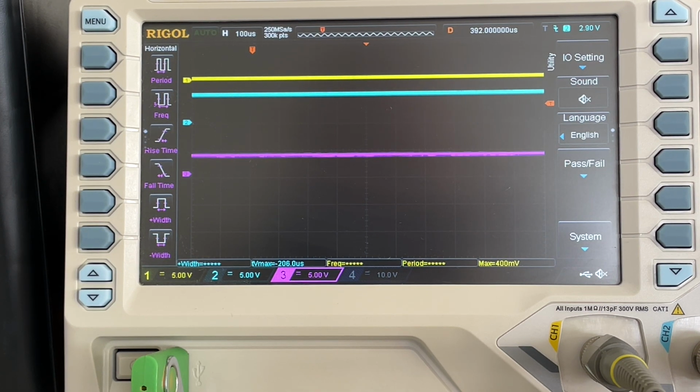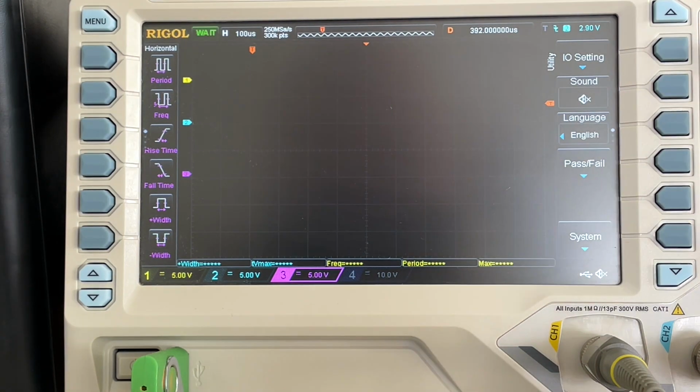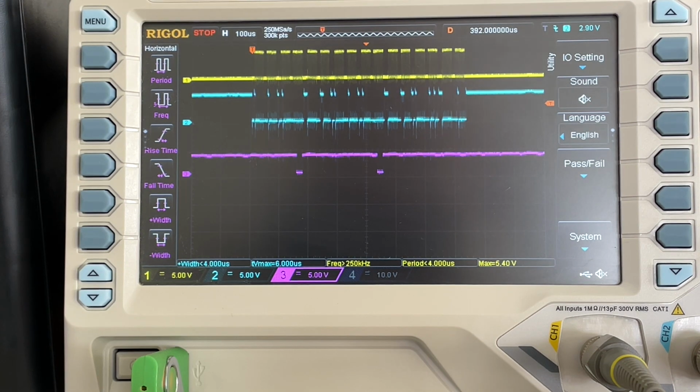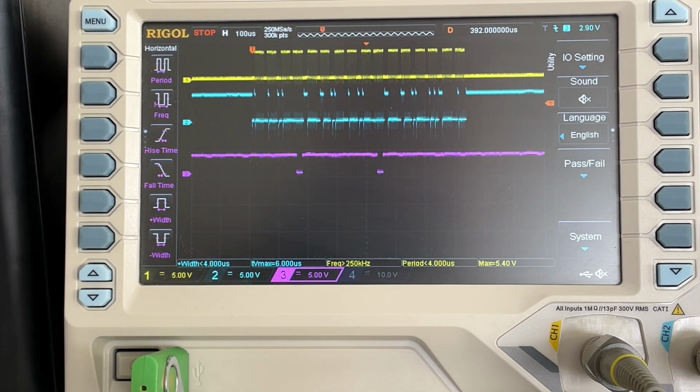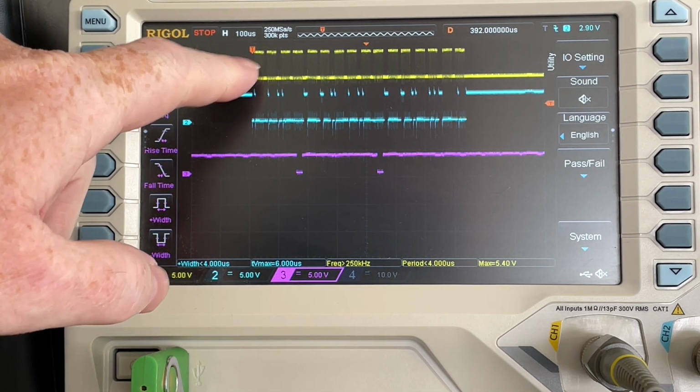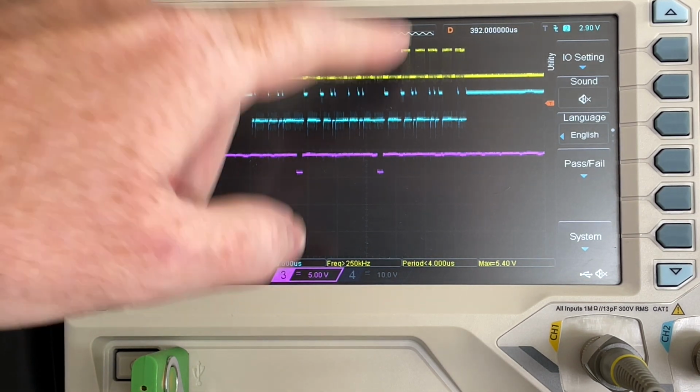You can see that the clock is currently idle at the low signal, whereas the data output from the computer is high. So let's tell it to trigger on the clock signal, and then I'll do a simple operation, just entering it here. Okay, and here we can see a sort of protocol exchange between the computer and the video board. Even at this level, if we look at the clock signal, you can see a bunch of sets of signals: 1, 2, 3, 4, 5, 6, 7, 8, 9, 10, and so forth.